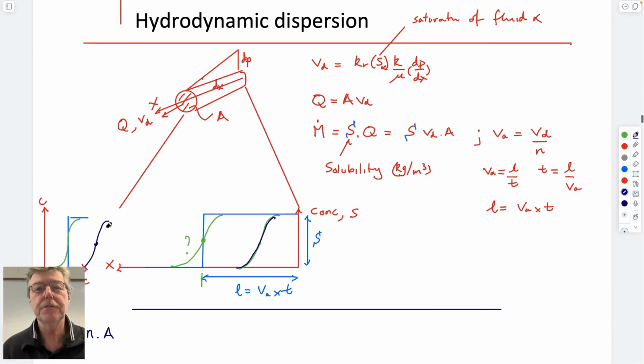So the bulk motion of the flow is Darcy velocity, and that represents, if you multiply the total area it flows through, which includes the quartz, which it doesn't flow through, then that would give you the volumetric flow rate Q. If you want to know how quickly it travels downstream, it's that velocity divided through by the porosity, because it allows for the fact that it's only flowing through the open part of the pore skeleton, and therefore a given volumetric flow has a velocity which is much faster because it's being squeezed through only 10% of the cross section.